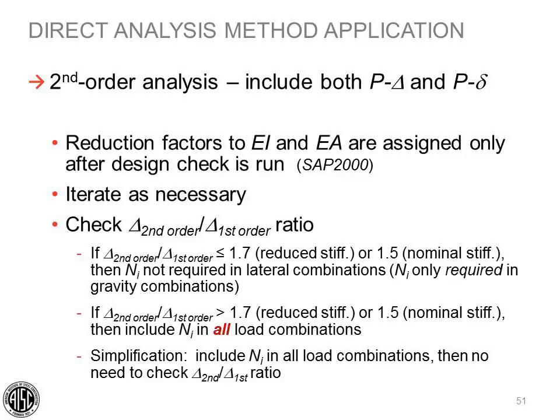Would it be overly conservative to always use the 0.003 alpha y sub i to avoid calculating tau sub b? Good question. I don't think it would be overly conservative. Certainly it's not required. When you look at the 0.003 Y sub i for a typical structure, at least one that I'm typically used to working with, compared to the lateral loads that are applied, say, for wind or seismic, they're usually fairly small compared to those wind or seismic loads.